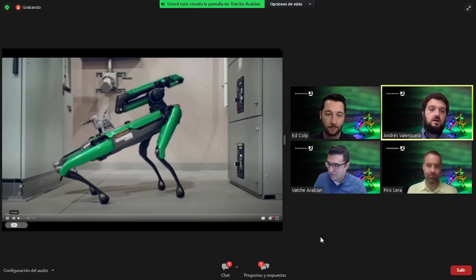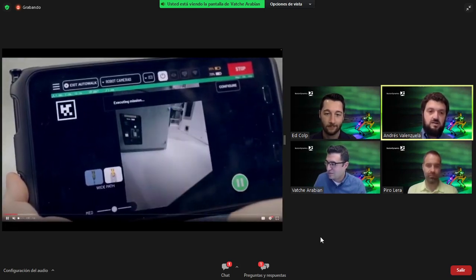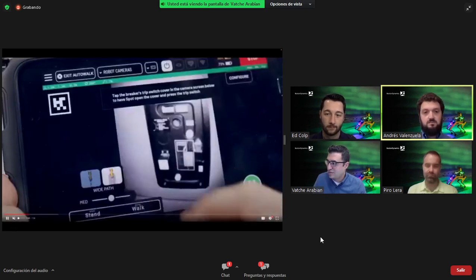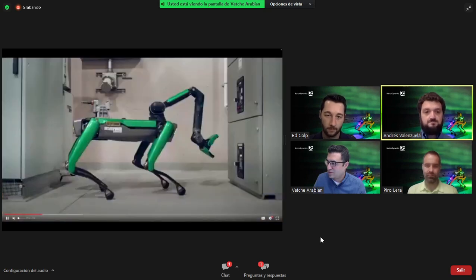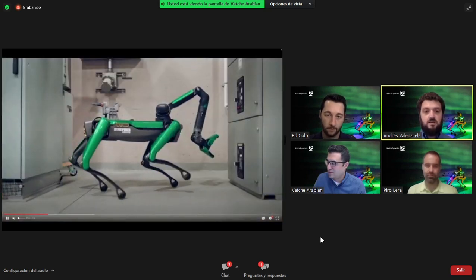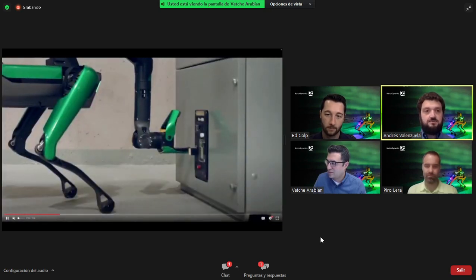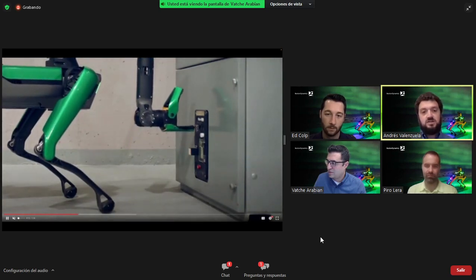So here, Spot is carrying a tool, and it takes a picture, and the user indicates where the breaker is by tapping on the image in the tablet. And then we get a closer look from the gripper and repeat that. And then Spot's going to go ahead and do a final fine localization step by touching off against the emergency trip switch cover. And this is going to give it the accuracy that it needs in order to push the trip switch that's under that cover.